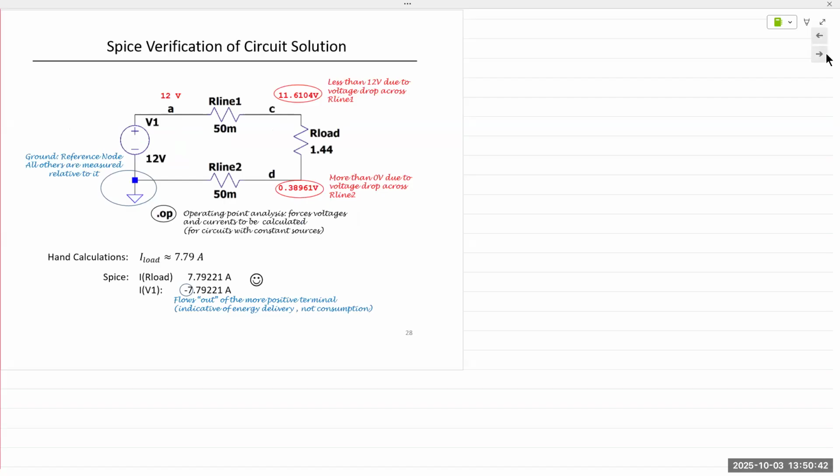If you have a circuit created in LTspice, it always requires a ground label or ground node, which is labeled right here. And what LTspice is going to show you, when you hover the mouse cursor on top of a specific node or along that wire, is in the status bar at the bottom left corner.